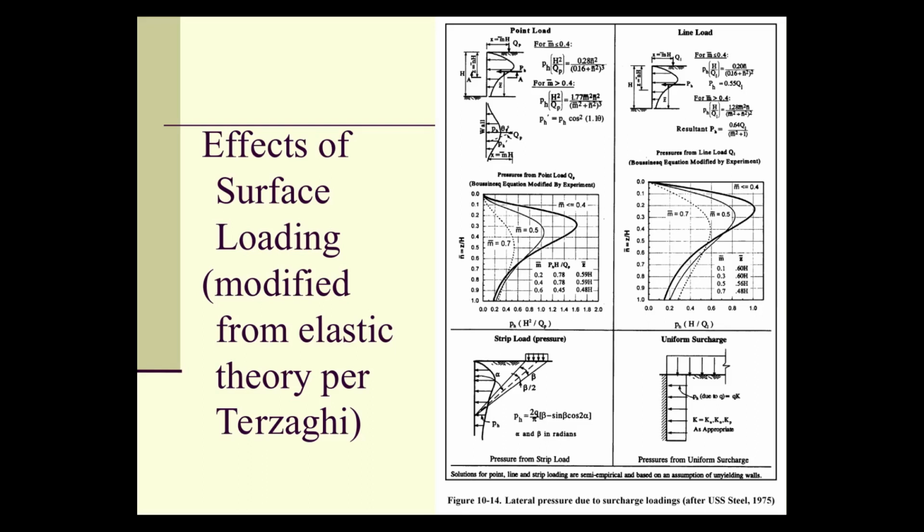The one exception to all this, in terms of theory of elasticity, is the uniform surcharge. And as I mentioned before, and this is exactly the same as in that slide from the FE exam thing, the uniform surcharge pressure is equal to the uniform surcharge pressure times whatever lateral earth pressure coefficient is appropriate.